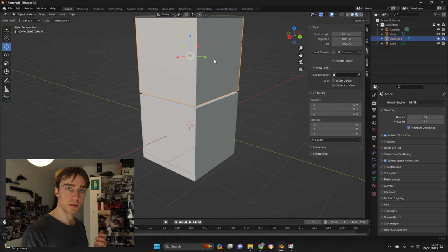But it does take up more render time. So Alt-D is great if you want to have a forest, a bunch of trees that are identical, and you just rotate them a little bit so they look a little bit different. It'll take up less render time. And then Shift-D is if you have a house, but then you want to Shift-D duplicate it and tweak a few things.